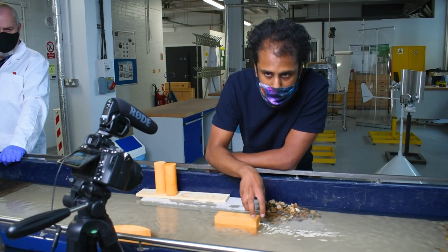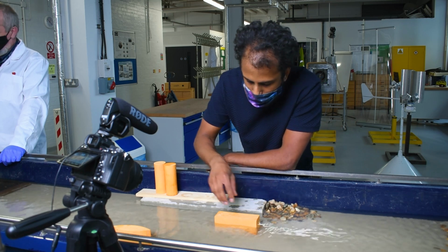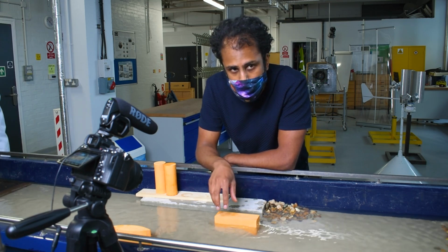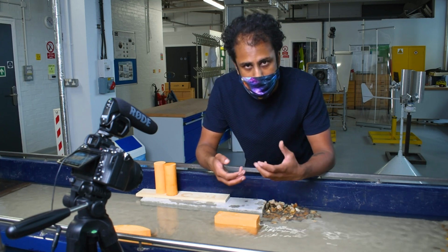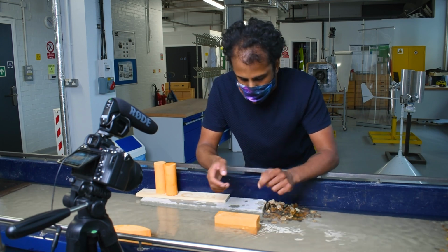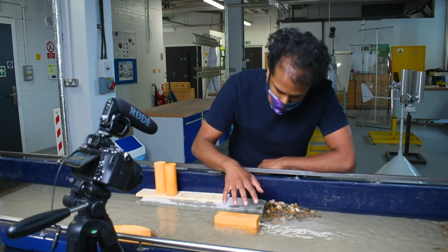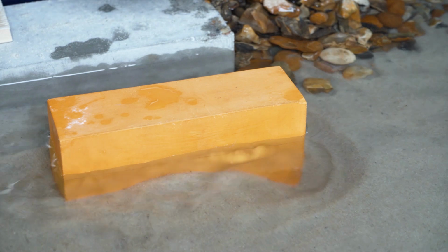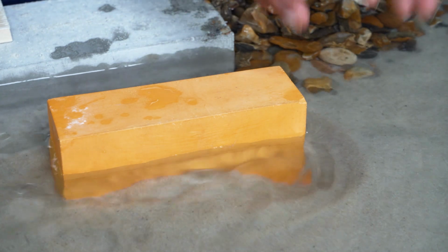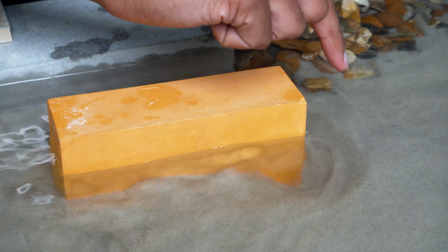So there's a scour hole developing on this side, and it's still going, and there's deposition on that side. And so the loading profile from the sediment on the structure is changing. If you look very closely, you can see where the extent of the horseshoe vortex is at the front of the structure, because there's a little concentric circle.